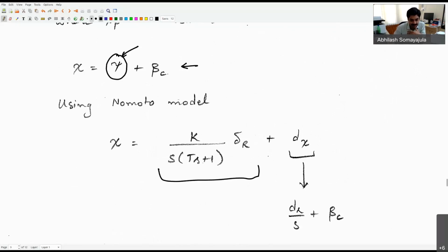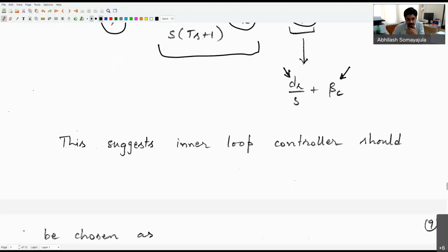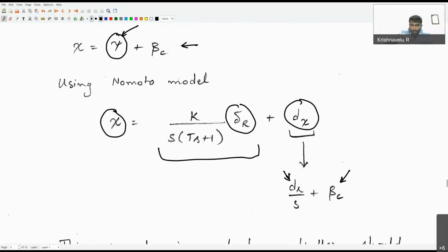Okay, so then what has happened is we have basically expressed our course angle chi in terms of the rudder angle delta plus some external disturbance, which includes an actual external disturbance and the effect of the crab angle. All of that we are lumping together into the so-called new disturbance term, which we are calling di. What is beta c? Beta is the crab angle. This is tan inverse of v by u.